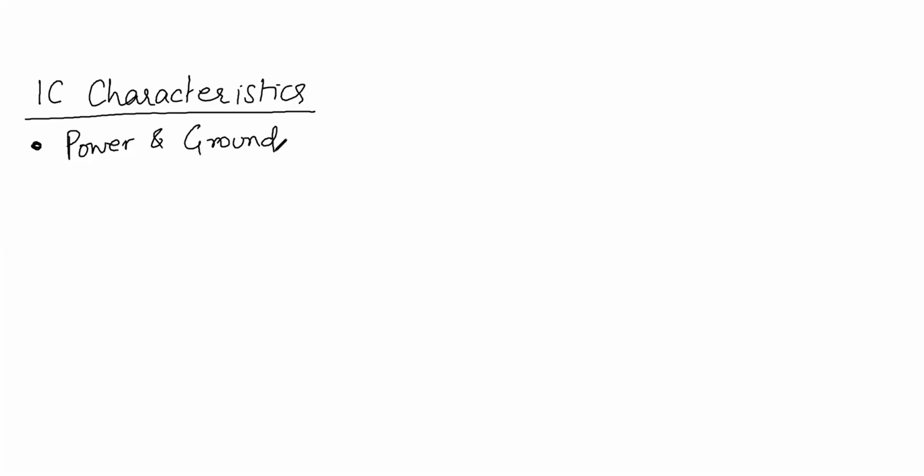Though if I'm using a system which is operating on 5 volt, but I have an IC which is 3 volt, if I connect 5 volt to this IC it can burn off. It will not show the predicted behavior of the IC.